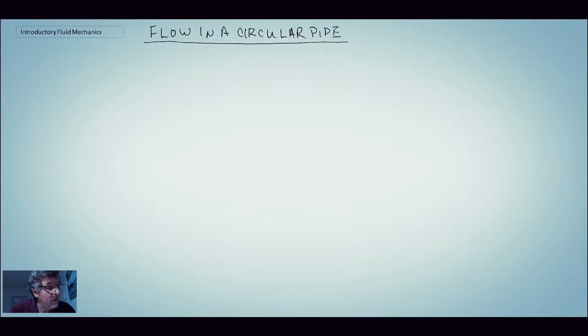And what we'll do is apply the energy equation to that section, and we will also apply the control volume analysis, specifically the momentum equation along the axis of the pipe. And with that, we're going to come up with a relationship that is going to move us one step closer to being able to resolve pressure drop within pipe flow. So let me begin by drawing the schematic, and then we'll work through the energy equation and the momentum, and then we're going to do some dimensional analysis.